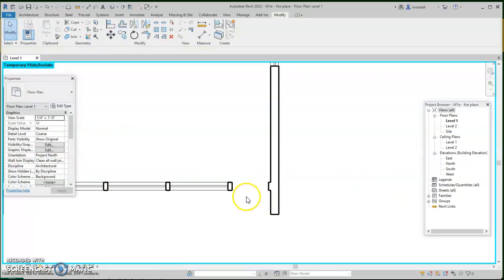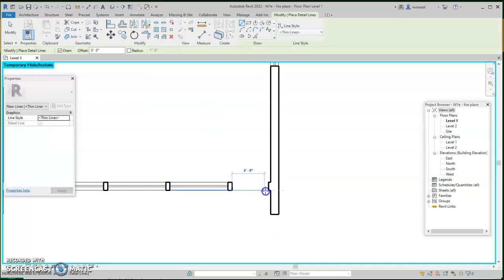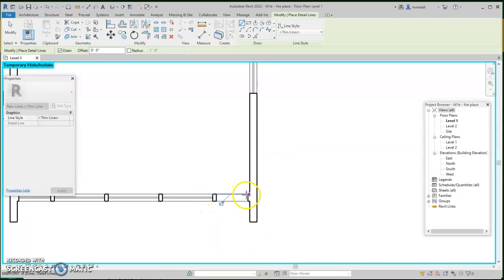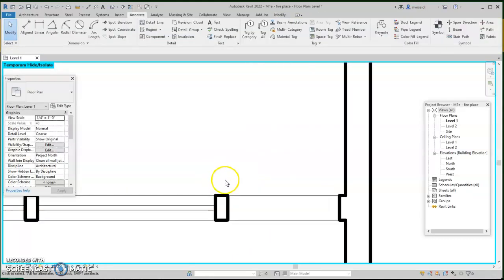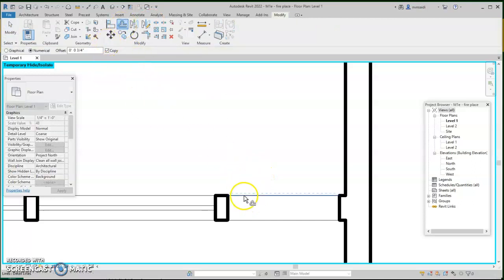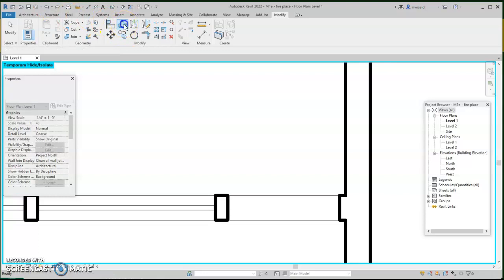This one is actually a door swing. First, I'm going to annotate, draw the door sill in a symbolic way. It's not actually, usually you have a projection. Now, let's go ahead and draw the other door sill line. Now I'm going to offset, and I just pick this line, offset 3/4, but I'm going to pick this line and that represents my door swing. If I offset 1 inch, I think it looks more realistic. So I'm going to go 1 inch inside, 1 inch inside.